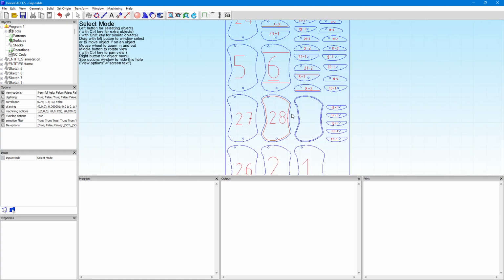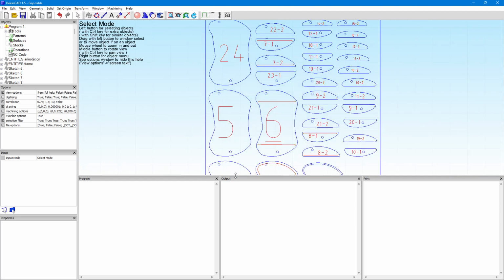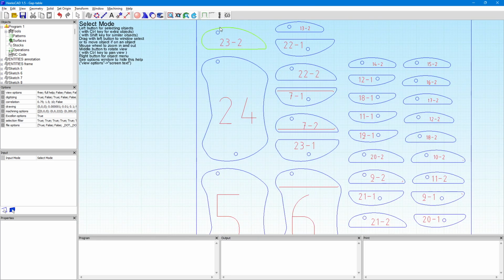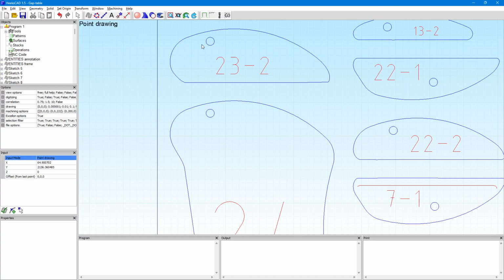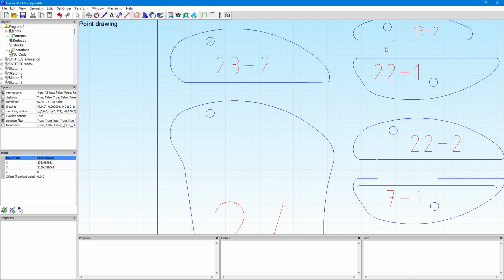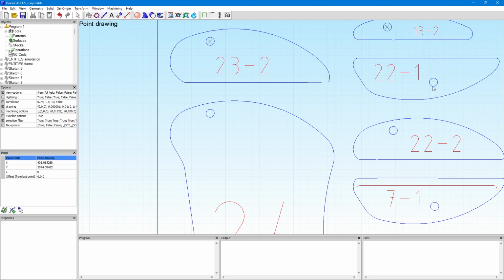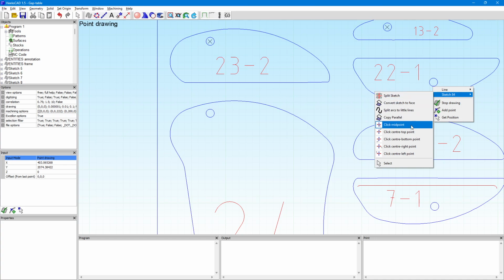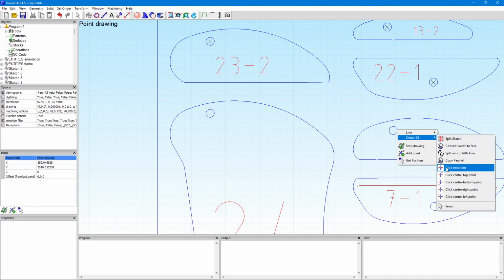So what I can do is I can do the cutting, making the holes is first operation. In order to do the hole operation, you will need the center points for the holes. So make sure you've got center endpoint on, and start drawing points, and right click the circle, go to sketch 69, and there is an option for midpoint. Right click, click midpoint, and individually I have not yet found a way to put the centers all together, but right click, select, and you put the midpoint.